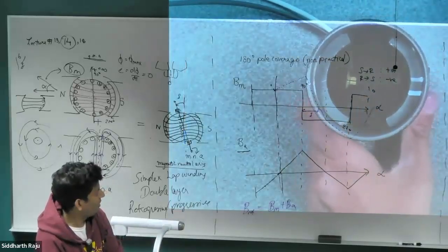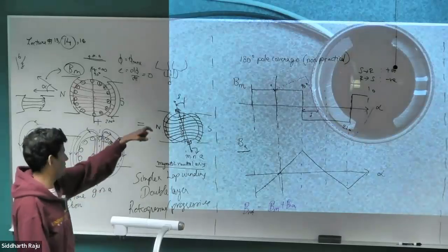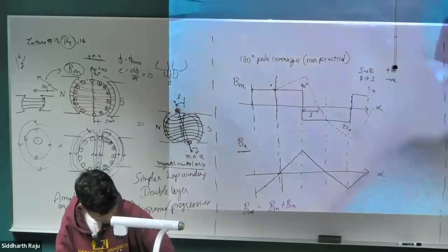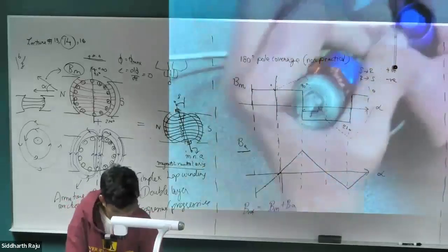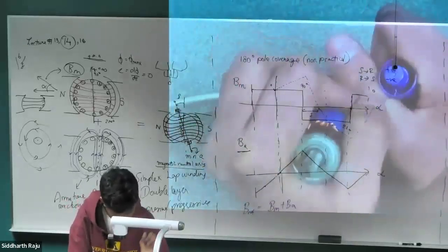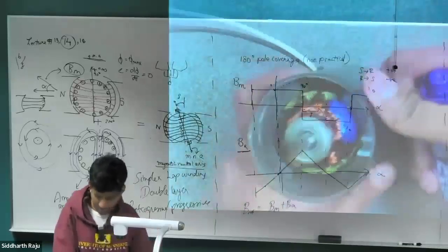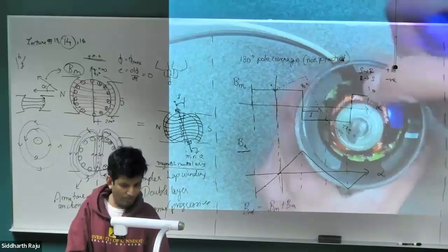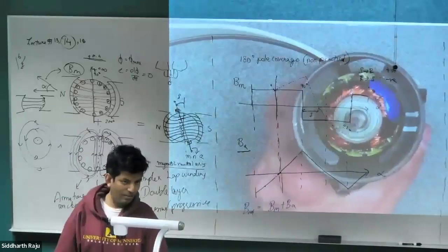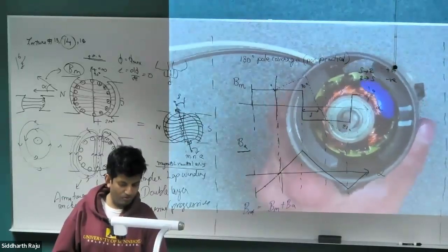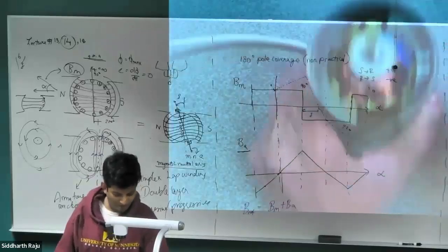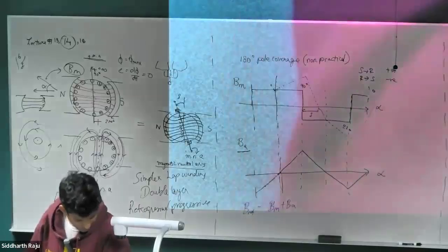So if you look at the poles there, the way I've drawn it on the board is not the same way the poles are there. Once I put the rotor structure inside, you can see that some of the conductors on the top do not get covered by the full magnet. Right? There's a portion where the magnet does not cover the full set of coils, the rotor armature slots that we have. And this creates what's called a saliency.